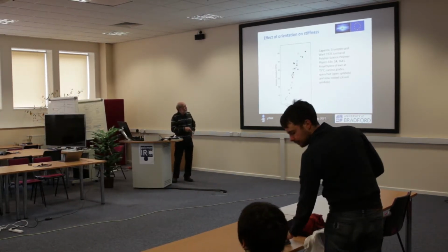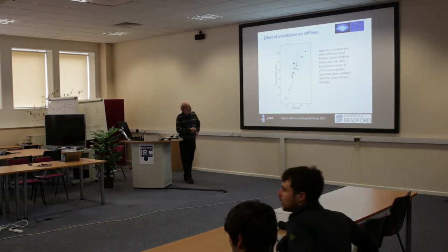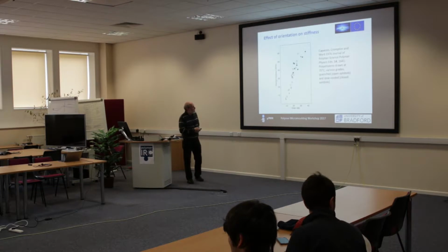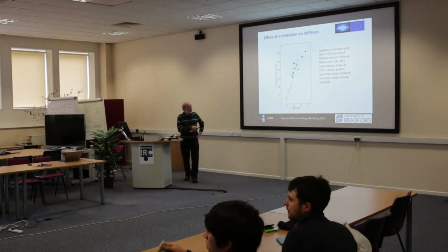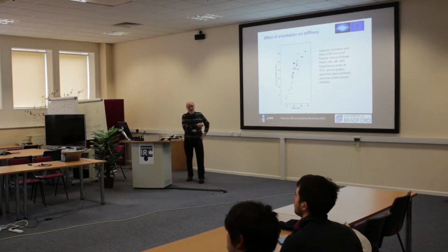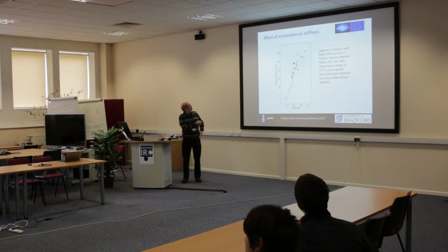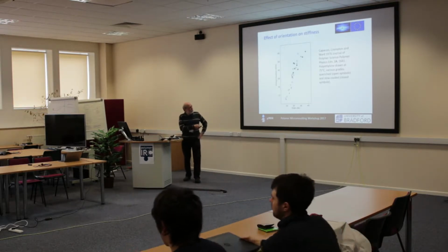And the draw ratio, the extension you've applied, goes up to about 30. And you can see the modulus goes up. The undrawn stuff isn't actually on the graph, but it's around 1 gigapascal. And you take the modulus up to about 60. And you've only drawn it by a ratio of 30.